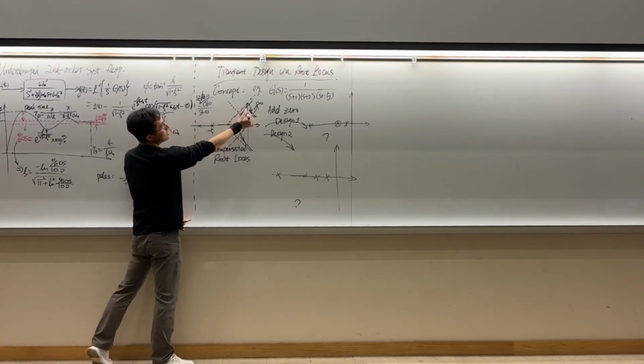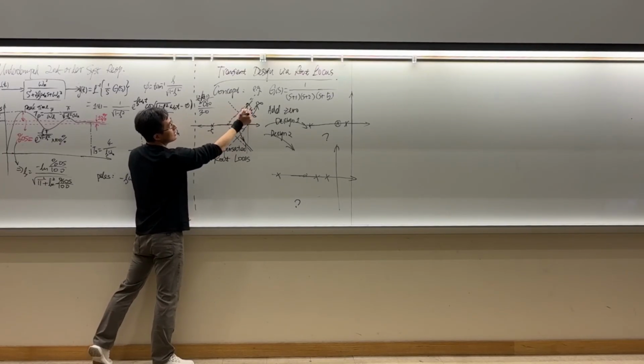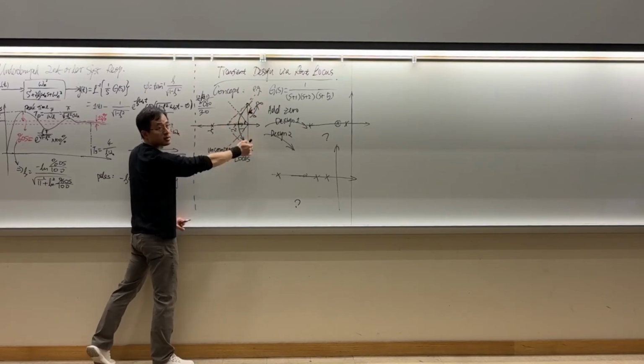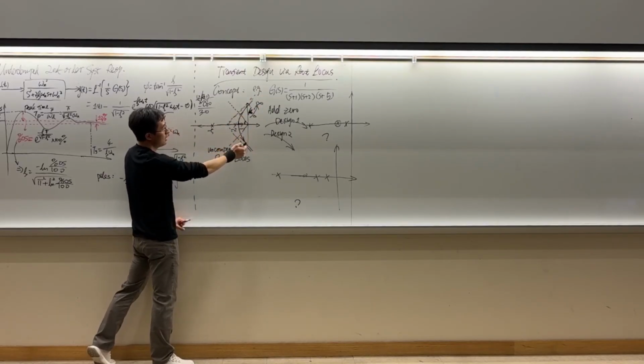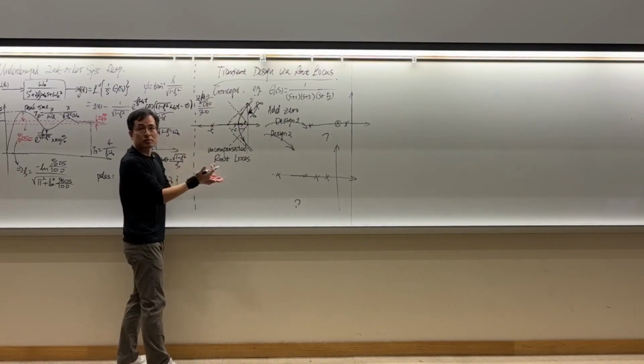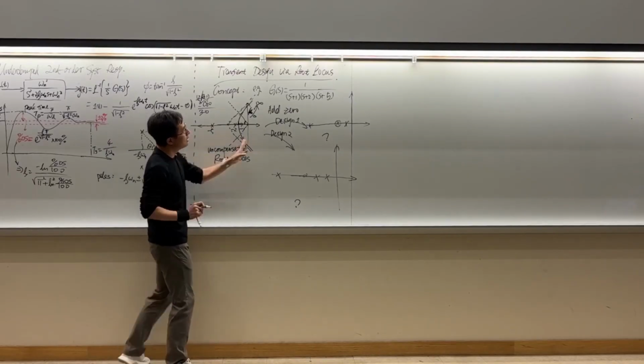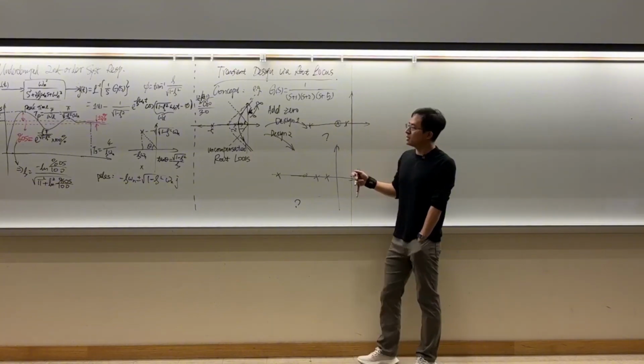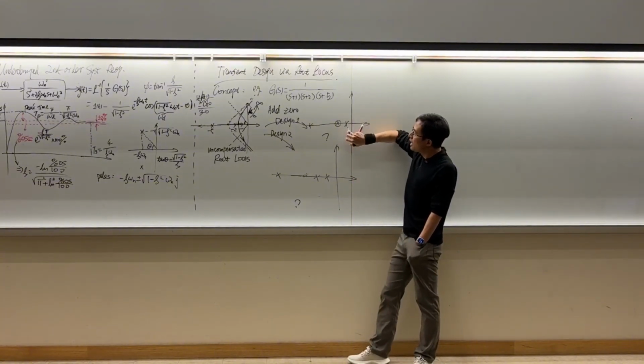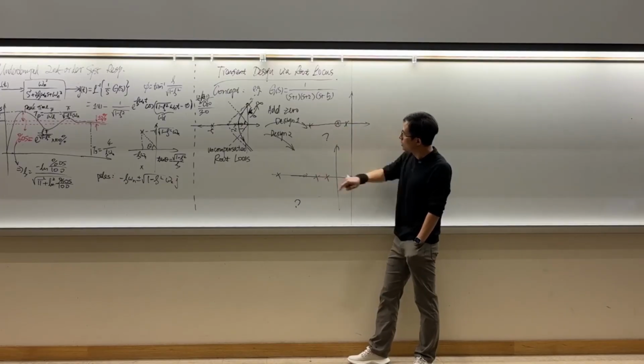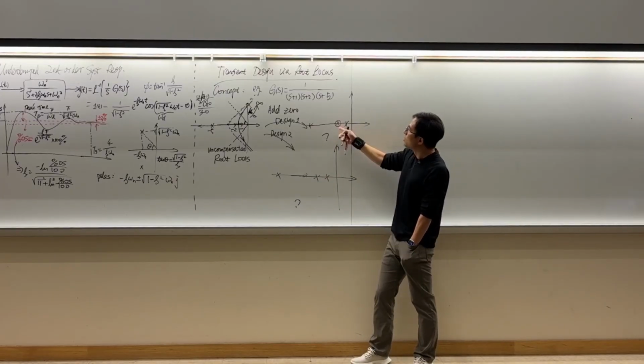We know that we can design the closed loop to have stability, right? It doesn't go to the right-hand side of the complex plane. And we know it's an approximate second-order response. Now, let's see, using the root locus technique, if you design, I have two designs over here, you add a 0 to the system. This 0 is exactly located at the pole location.